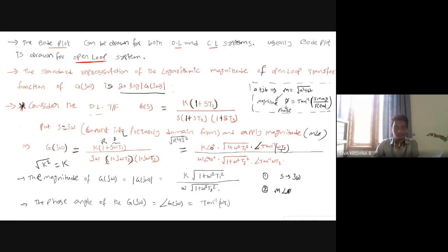Yeah, next one. What is the next term? Are there any terms in the numerator? Is it completed? So next, coming to the denominator. Here you have only an imaginary term. So for this also you can take real part square, 0 square, plus imaginary part, w square. So root over w square is w only. So directly I am writing w here, and j means 90 degrees angle.